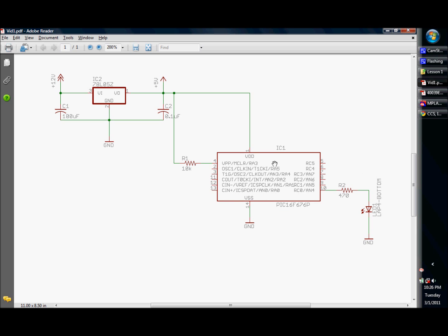However, I'll show you later, there is an internal fuse setting, or basically a configuration bit, that you can set that will internally tie that to a high and save you the resistor. If you know your application is not going to use a reset button, then that'll save you a component. But for right now, I just want to get you used to seeing that. Later projects will probably be using the reset button, and so we'll need that 10K, so just get used to seeing it.